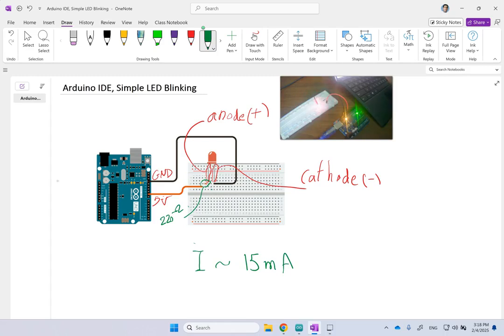And then there is a voltage above which the LED is going to turn on. That voltage for this LED is about 2 volts. So the forward voltage you pass to the LED should be bigger than 2 volts for it to even turn on. When we talk about diodes, we'll cover this. An LED is a light emitting diode, and diodes, especially this one, need at least some minimum voltage in order to let the current pass. That is like 2.